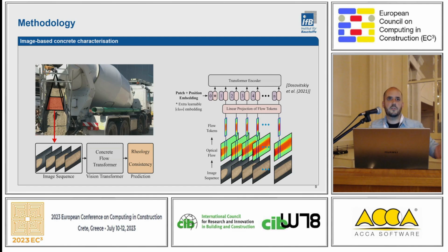And as a standard for regression or classification problems, we add a learnable class token to the sequence, and the whole sequence of tokens is then fed to the transformer encoder. And we implemented a multitask head on top of the encoder, one regression head which predicts the real values for rheology, so the viscosity and yield stress, and a classification head which predicts the consistency class of the concrete.